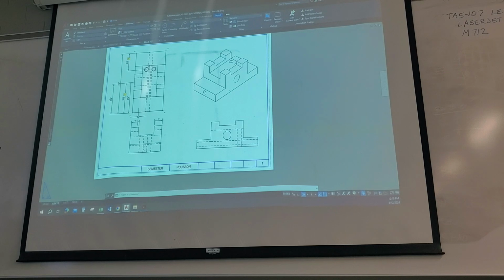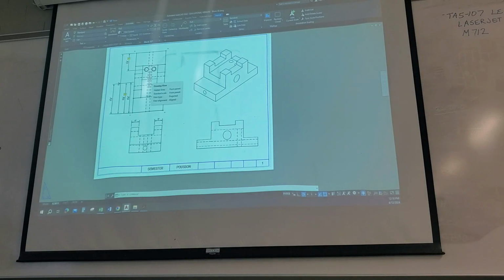So after you do your dimensions, you do your labels. Now, I don't remember if I showed you, yeah, I did on this little view up here. We're going to talk about your 2 objects in a moment, but I showed you a north arrow up there. When you label your views, remember, do not show a north arrow, do not call it a plan view and elevation views. Just call it your standard top view, front view, right side view, and ISO. Don't show the north arrow on your finished product when you turn it in though.